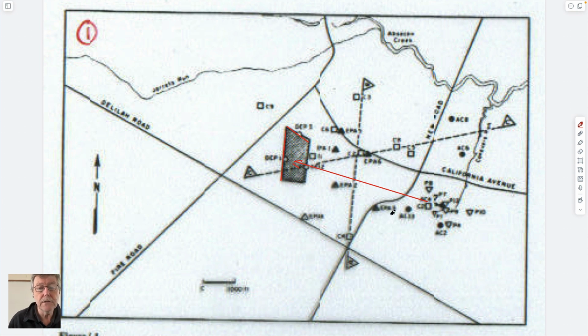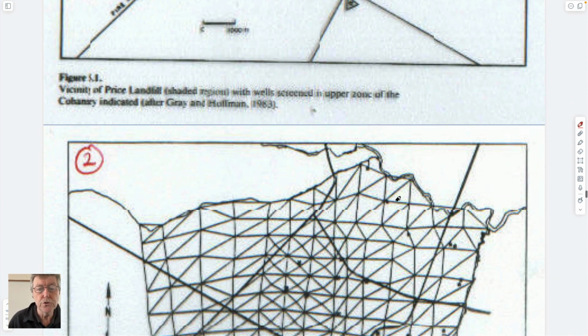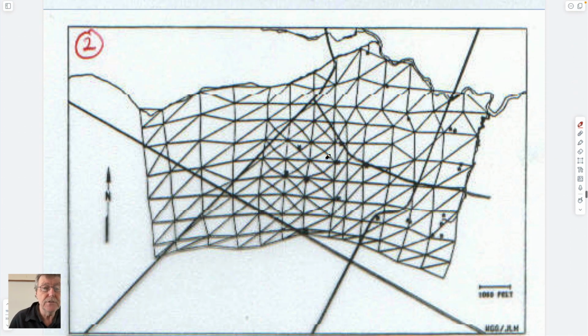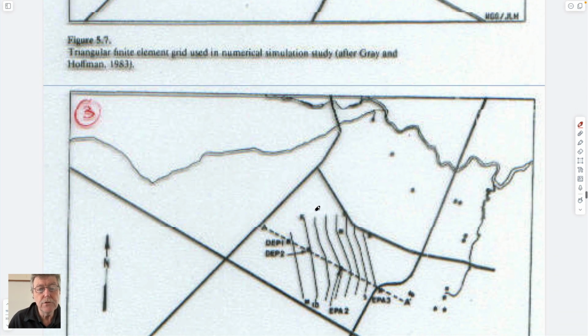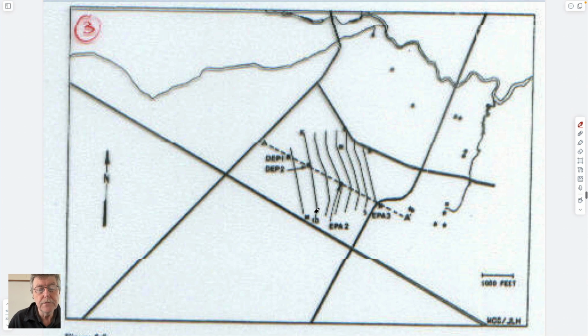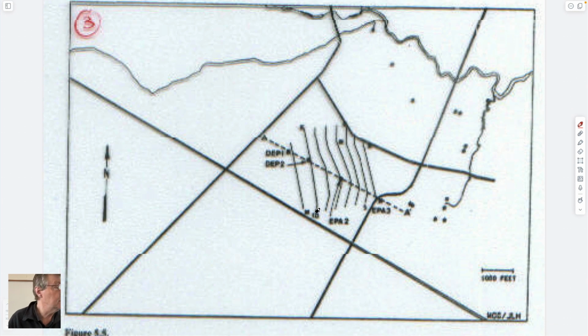So if you end up being able to draw the contours, and you take all these existing wells where you have the individual heads at these nodes of this little mesh that you have here, and you know what those heads are, then maybe you could run a model to predict the distribution of heads.